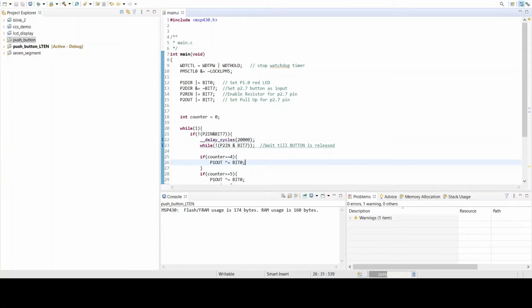The main difference is that in polling, the CPU keeps continuously checking for the device status, whereas in an interrupt, the device signals an interrupt, and then the interrupt handler does whatever processing has to be done. So of course, interrupts are more efficient and are used in a lot of modern OS. But for the sake of this assignment, we are demonstrating polling using the MSP430 microcontroller.